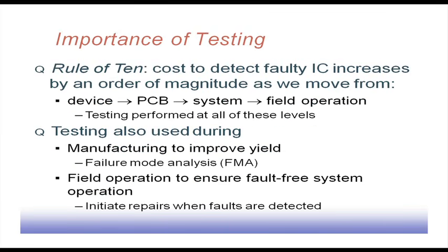Now, testing is required to guarantee fault free products. We want this product to be fault free. So, how to ensure it? It has to be ensured by testing, because even if my manufacturing process is 100% correct, we cannot say with guarantee that the fabricated chip will be fault free because of impurities in the silicon. Plus, there are defects from manufacturing process variations, etc. We can never make the manufacturing process 100% correct either. So, testing becomes an important issue.